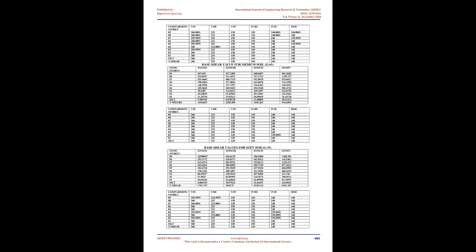3.6 Horizontal layout. Generally, buildings with simple geometry in plan perform well during strong earthquakes. Buildings with reentrant corners, like those U, V, H, and plus shaped in plan, are subject to severe damage. Often, simple plans with columns and walls unequally distributed in plan tend to twist during the earthquake.